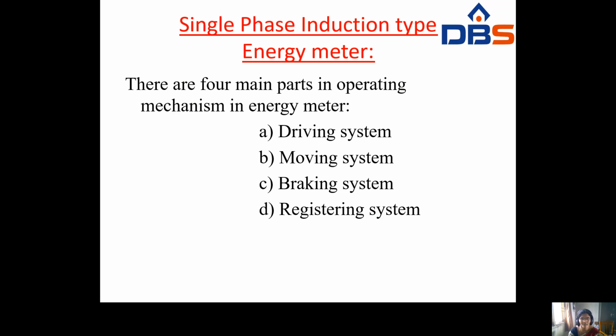Single phase energy meter is also nothing but the single phase induction type energy meter. That means for single phase, to find out the energy value, we are using the single phase induction type energy meter. There are mainly four parts in the operating mechanism of the single phase induction type energy meter. What are those? Driving system, moving system, braking system, registering system.